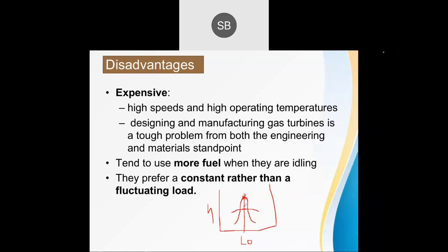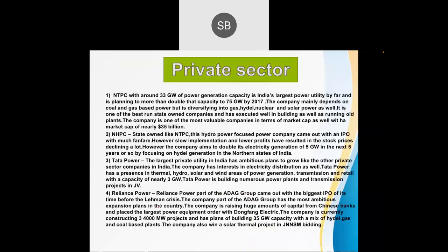The gas turbine is specifically used for power generation because in power generation, as we know, the load is not going to fluctuate. The load will be constant over time, and because of that, we will achieve the maximum efficiency for that particular period. Whenever there is no load or a fluctuation in load, the efficiency of the gas turbine reduces drastically, and because of that, we are not using the gas turbine in vehicles. So these are some disadvantages of the gas turbine power plant.